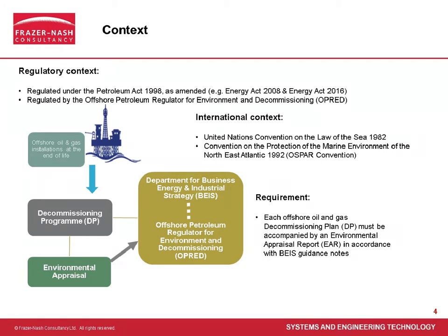The most significant obligations for decommissioning offshore oil and gas operations are set out in OSPAR Decision 98/3, which requires that the topside of all installations must be returned to shore, and that all steel installations with jacket weight less than 10,000 tonnes in air must be completely removed for reuse, recycling or final disposal on land. The decision recognises that it might be difficult to remove the footings of large steel jackets weighing more than 10,000 tonnes. Similarly, it acknowledges difficulties with removal of concrete installations.